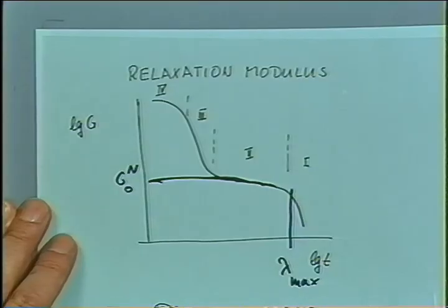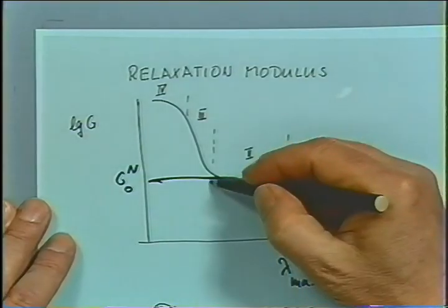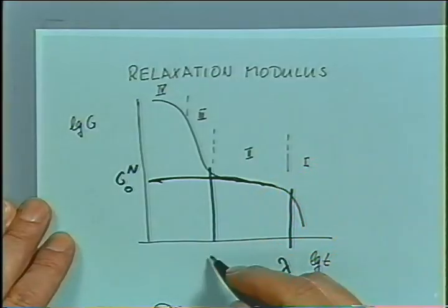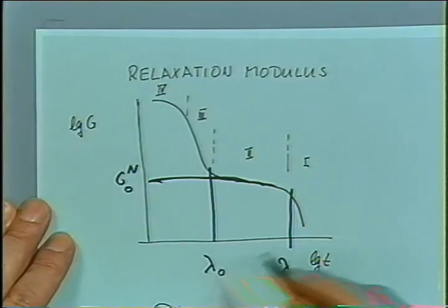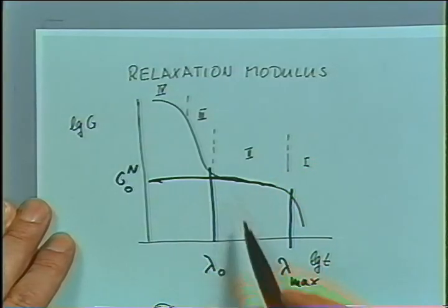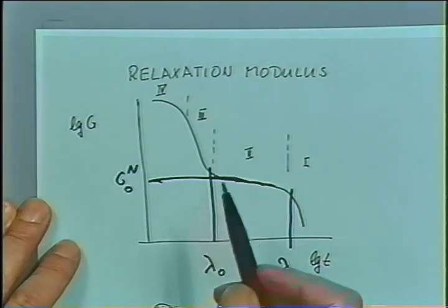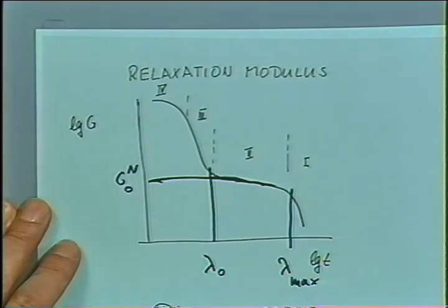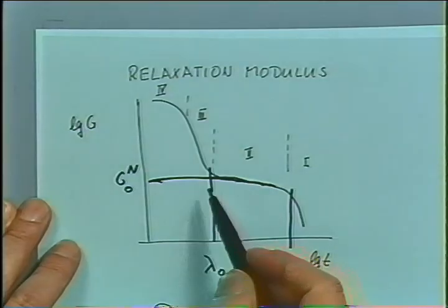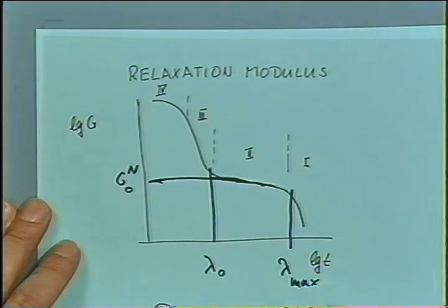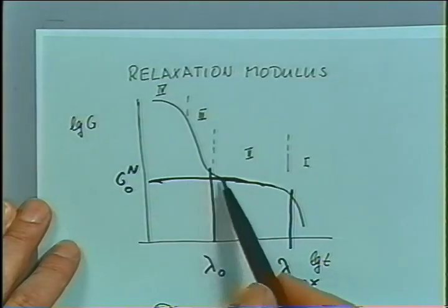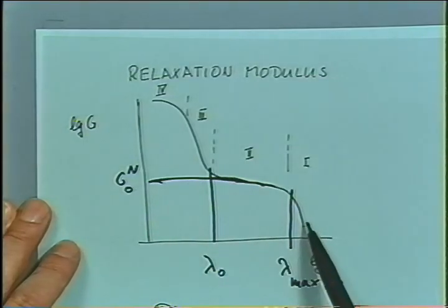We should measure that also. And then there is a shortest relaxation time for the plateau region, or you could say that characterizes the transition to the glassy behavior. If you observe your material at shorter time scales or at smaller length scales, then you will observe the glassy behavior of that system. Those three parameters are needed for the elastic behavior and for the flow region.